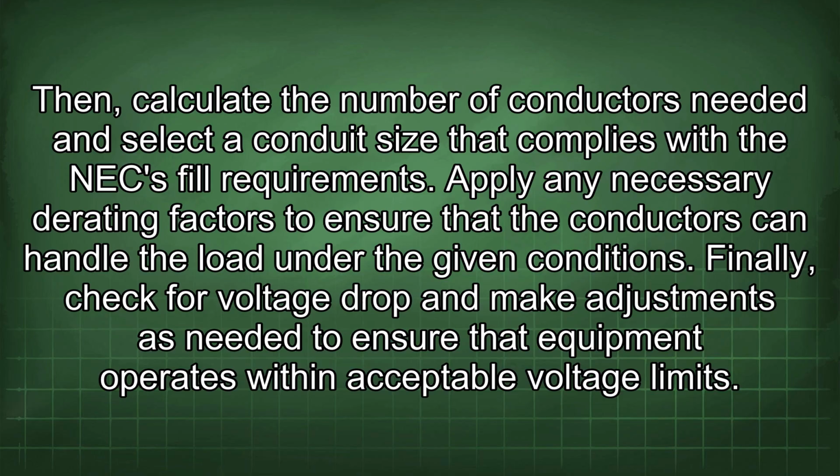Then calculate the number of conductors needed and select a conduit size that complies with the NEC fill requirements. Apply any necessary derating factors to ensure that the conductors can handle the load under the given conditions. Finally, check for voltage drop and make adjustments as needed to ensure that equipment operates within acceptable voltage limits.